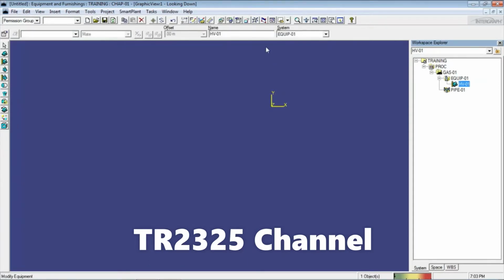Okay, then select the common view tool. Drag and drop here. If you select the corner, isometric view will appear. The north position will appear here. So the x-axis should be in the north position. In this case, we can rotate the axis using the arrow keys, left or right arrow key for rotation. The axis will appear in blue color, it's locked.